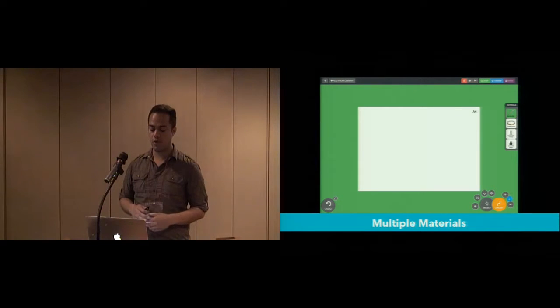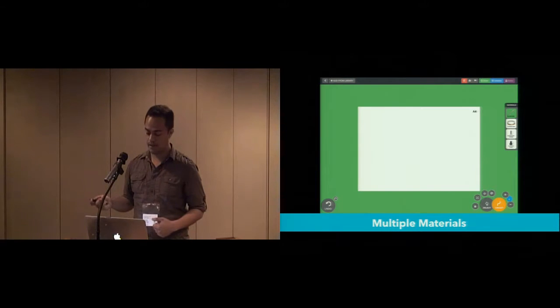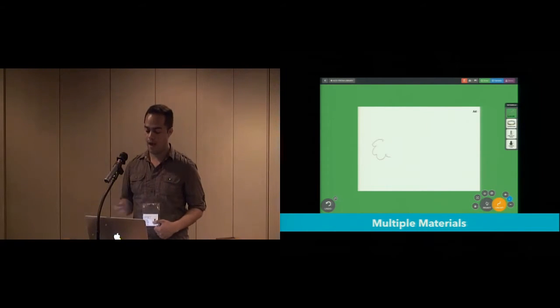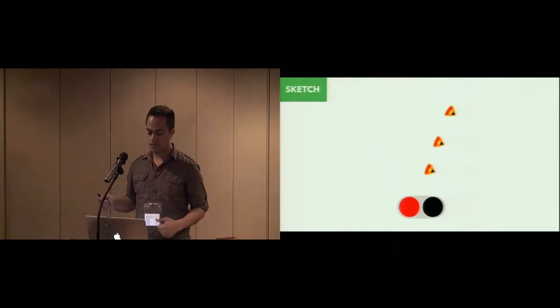Lastly, the circuit sketching domain has a widely expanding set of materials. We provide a palette of the most common materials, including silver ink, copper tape, conductive thread, and graphite paint. We compute the resistance of each material trace based on the model of sheet resistance, and more details are in the paper as to how we implemented this.